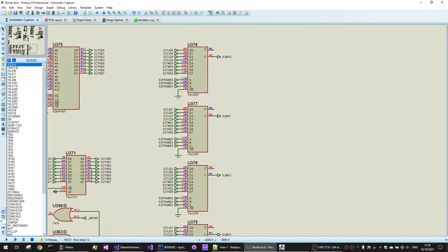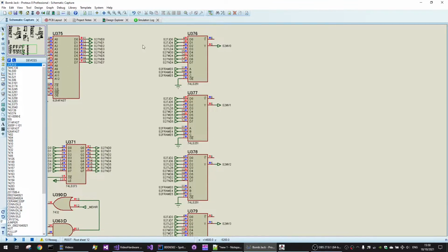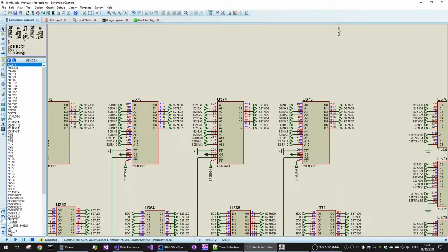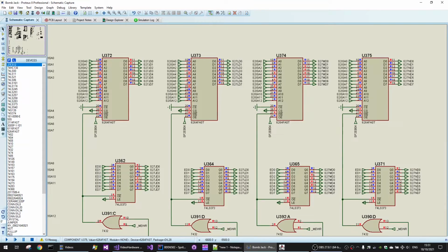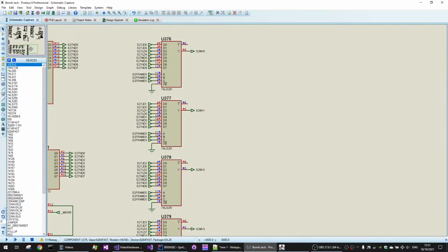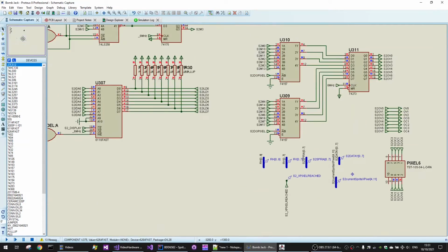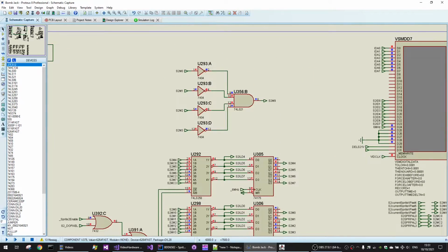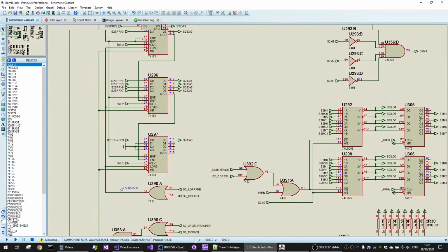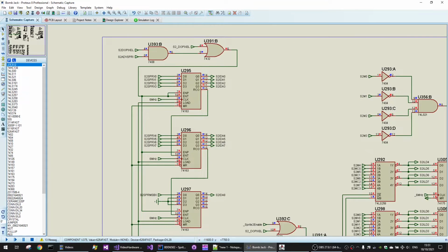And because it's 4 bits per pixel, it only has 4 of these, and the corresponding outputs here. This means, of course, that all of these sprite RAMs are reading different values, and that's why they just get deselected here, or selected from here. Now, we'll only really look at one sprite scanline logic because it's an exact copy, just using different even or odd signals to activate the logic appropriately.